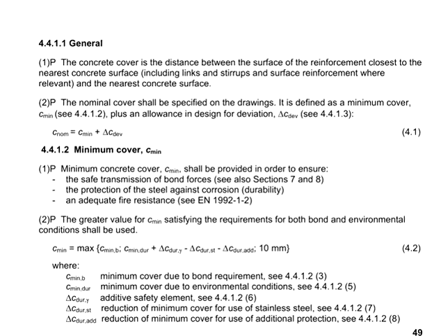In case it is being asked in the question, you may refer to the Eurocode, clause 4.4.1.1, equation 4.1 to determine the concrete cover. The concrete cover is determined by c-min and the deviation. The deviation is typically taken as 10 mm as recommended by Eurocode 2.